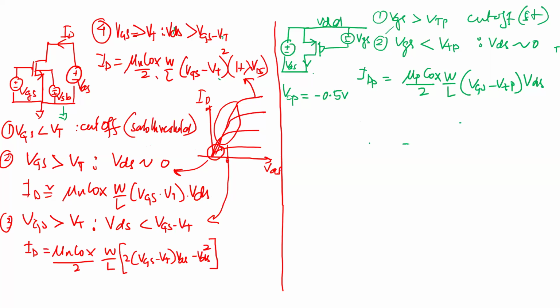So for PMOS, you remember the source is always on the higher side potential, gate is always lower than that, drain is always lower than that. On the NMOS, opposite. The source is always on the lowest potential, drain is higher than that, gate is higher than that. So at least know that from the circuit sense, and then you do.